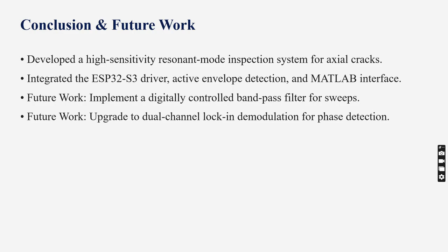For future upgrades, I recommend implementing a digitally programmable band pass filter to automatically adjust the bandwidth during frequency tracking, and upgrading to dual channel lock-in demodulation for complete impedance plane phase detection. Thank you, and I think that's all.